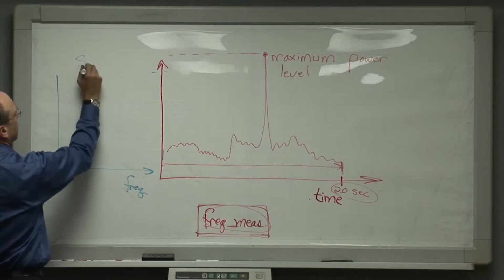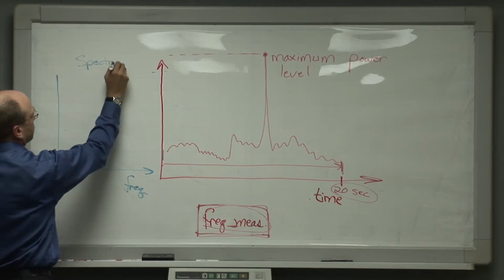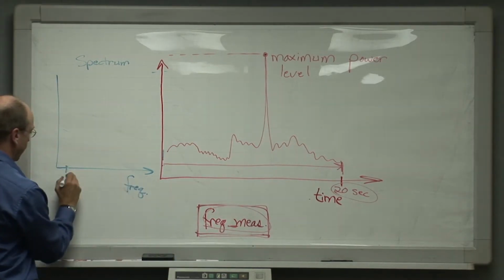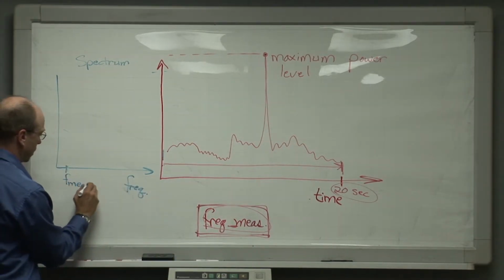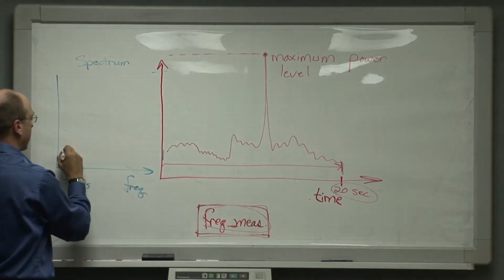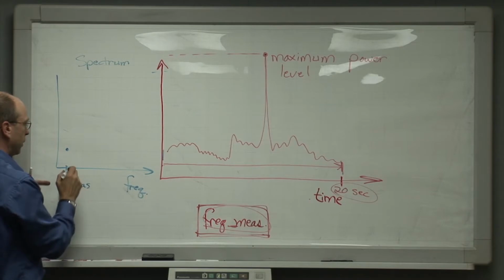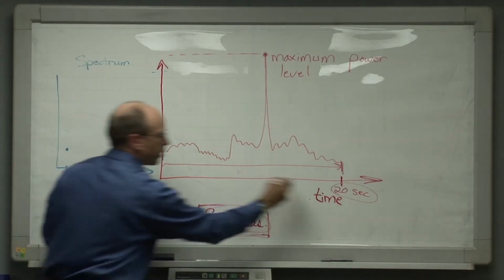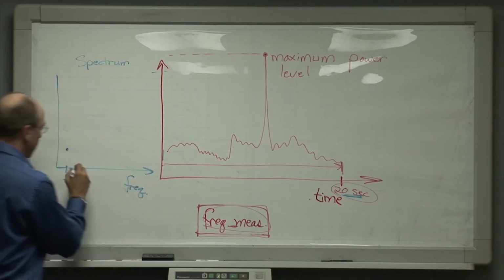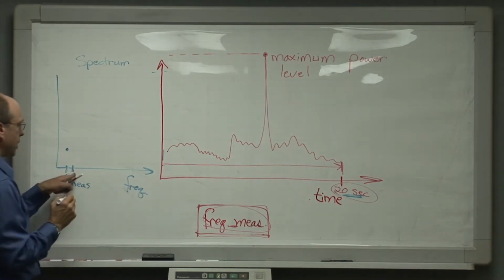This is the spectrum measurement. We know that at that frequency, fmes, which we'll draw right here, there's fmes, we know that the radar hit that power level right there, and that was the highest power level that it's going to put out in that direction because we waited long enough to make sure that we'd see a maximum amplitude hit occur. Then we step to the next frequency.